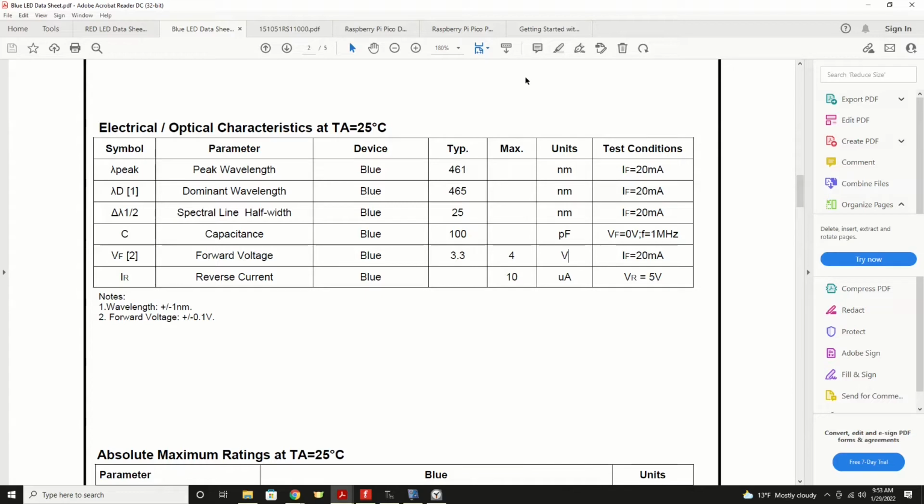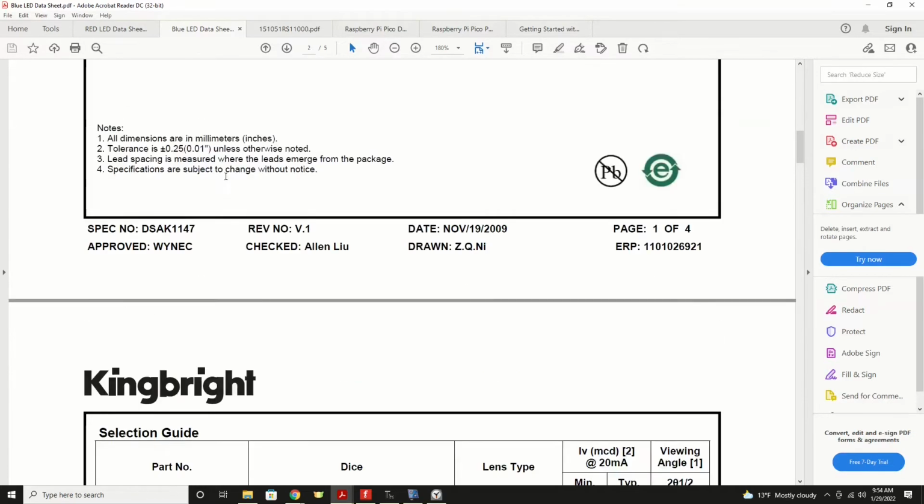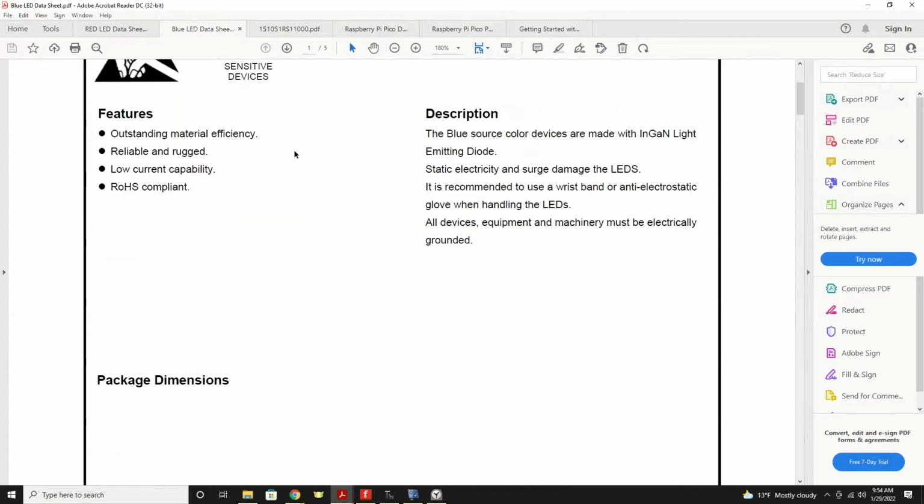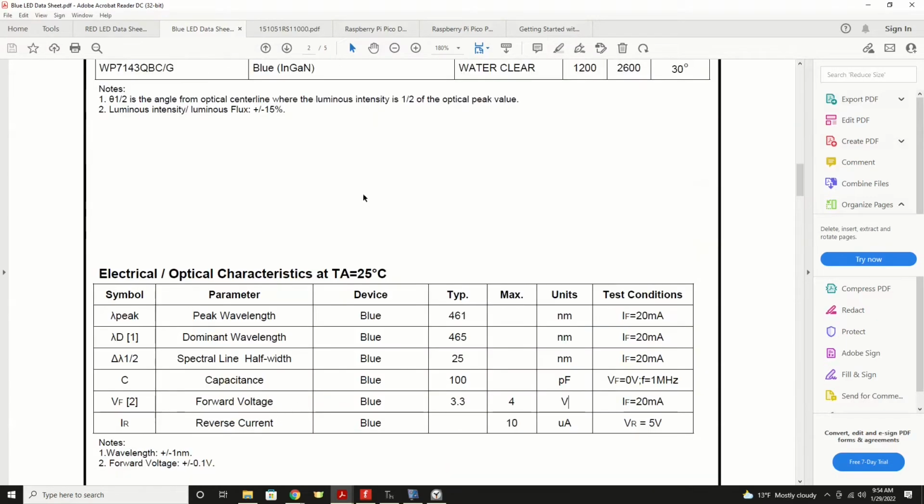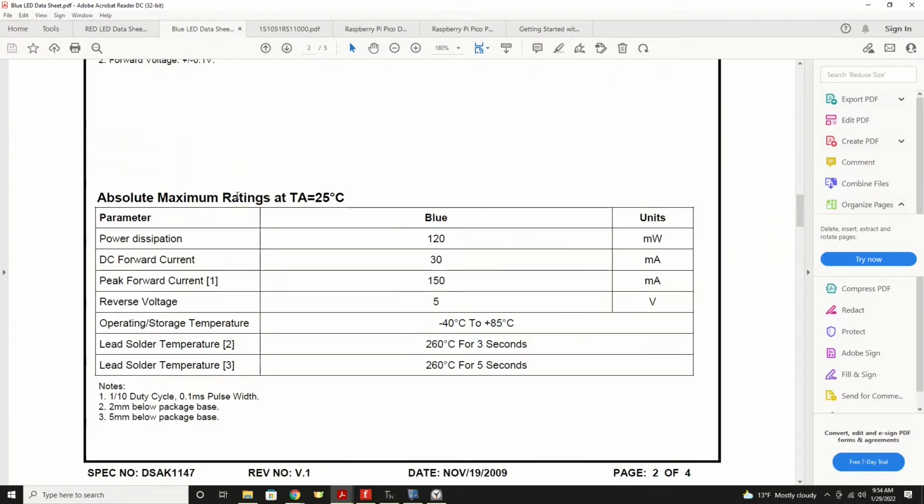I just wanted to take you through this process a little more engineering-like so that you know what you really should be doing. So hopefully you can find forward voltage and your forward current that's not at the absolute maximum, wherever that is on this particular data sheet. Oh, here it is. Here's our absolute ratings. Don't work in this area, that 30 max milliamps. Pick a number lower. So again, half of that from off to on would be about 15 milliamps. Target that, and you can go up or down a little bit.